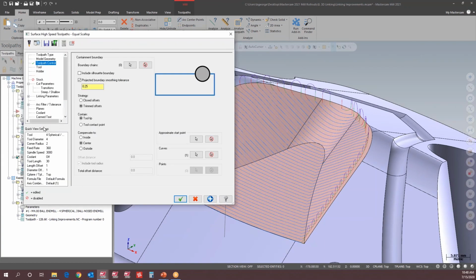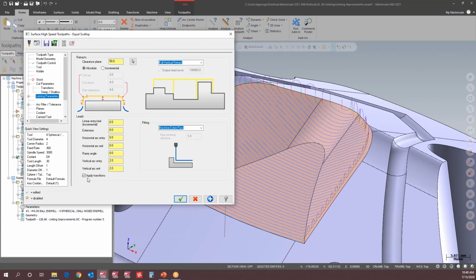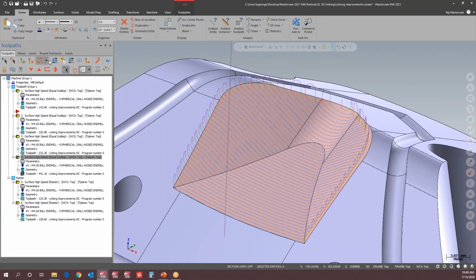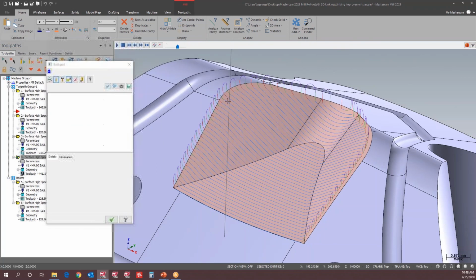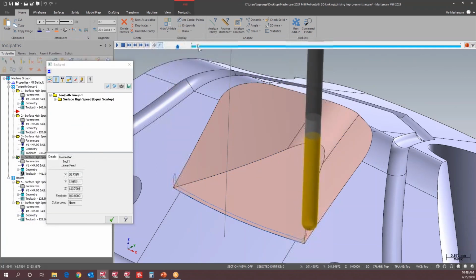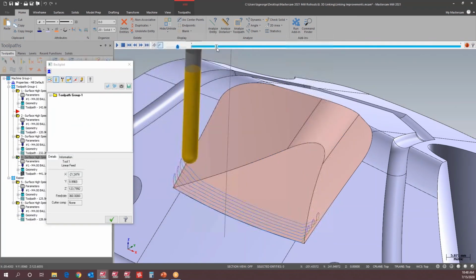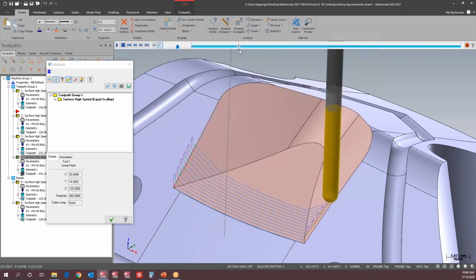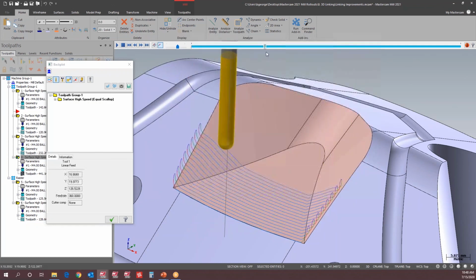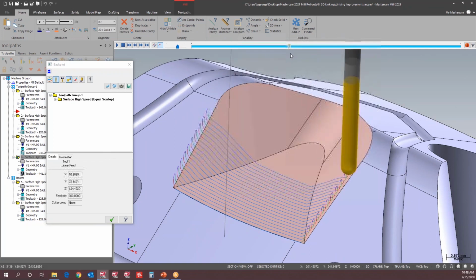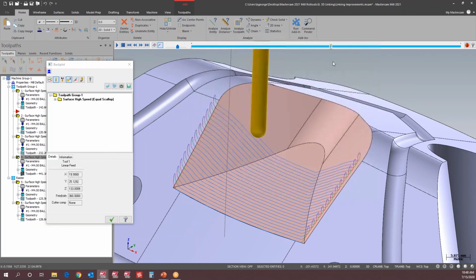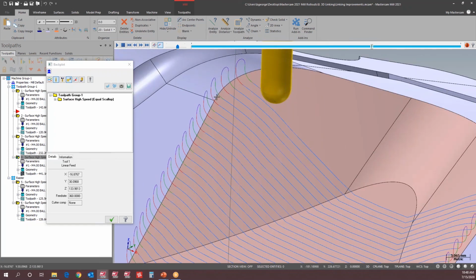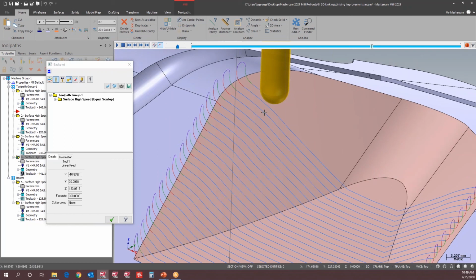With that option in 2020, plus our new option in 2021 of applying our transitions, now I can get this really, really cool toolpath that every time it pulls off the part, it's doing a sweet loop transition in between each one of the cuts. It's coming all the way off the part, looping around, and then re-engaging. So I'm not doing a hard start and stop right on the corner. I'm fully exiting the part, looping around, and coming back in.